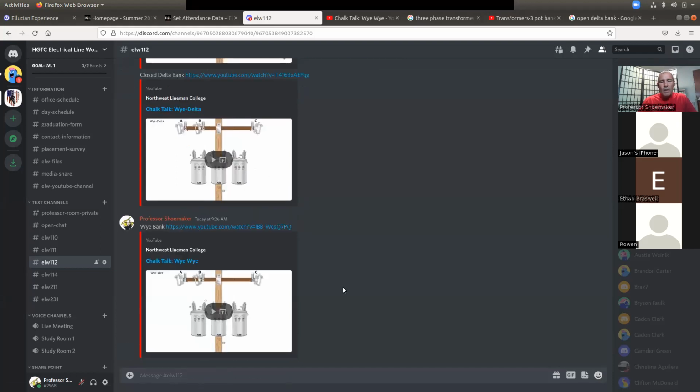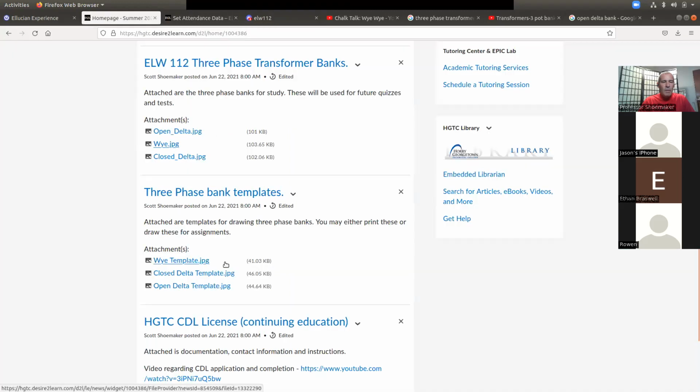Great videos to watch and study right there as far as those things are concerned, and getting your drawings down and everything right. The biggest thing to remember there is, what's the only bank that needs a transformer conversion? Why? I need to convert my Y, right? Where do I change my leads to? Well, yeah, you can use any bushing, but what is the wiring process? ACBD. There you go, ACBD.